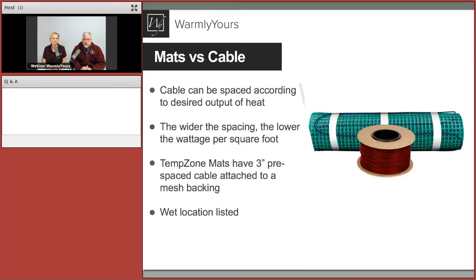Another question was from Maria, and that is, how can you ensure no hot spots for a 3/4 inch thick engineered wood? That really has two responses. One of them is that you want to always make sure that the heating product is close, because we know it only travels so far from each cable, right? Right. So we want to make sure that the final surface that your foot hits is no further than an inch to an inch and a half from where the cable is. And we want to make sure that the cables are spaced evenly. That's going to give you nice heat. If you get the cables too close together, it will get hot. So that's how you ensure you don't get a hot spot, Maria, is that you make sure that the cables are always evenly spaced. Excellent.